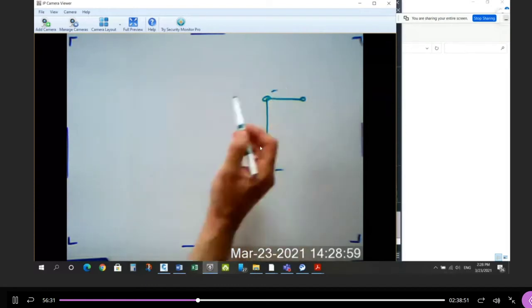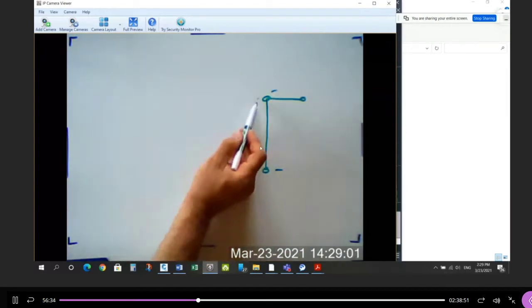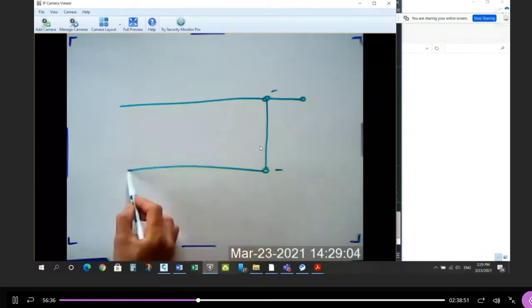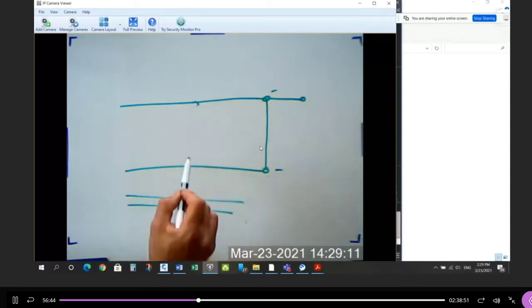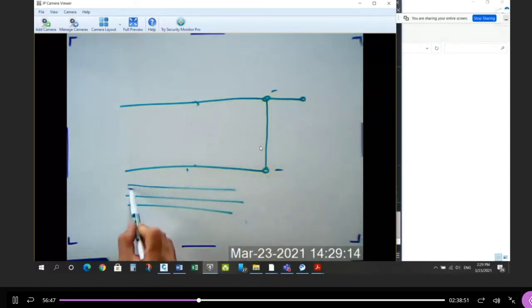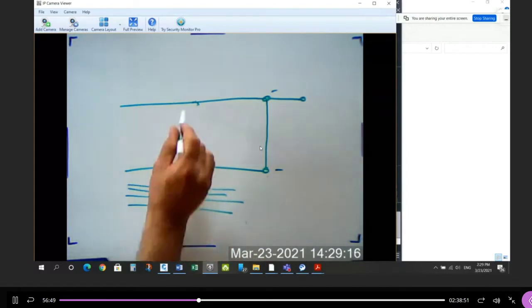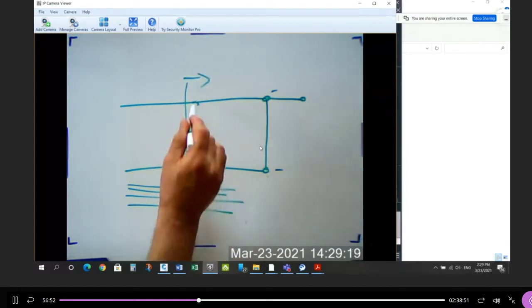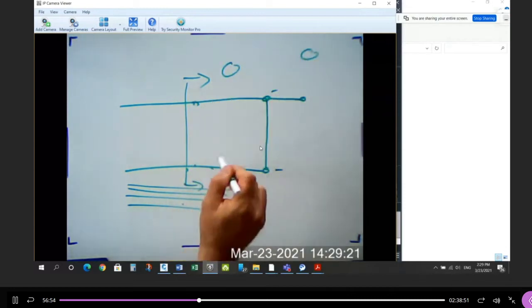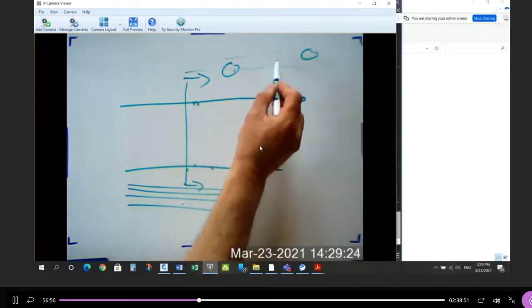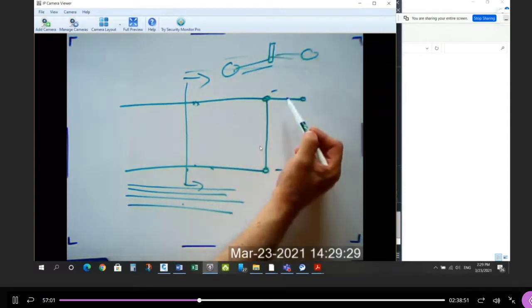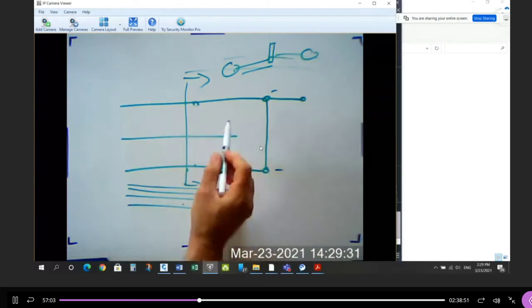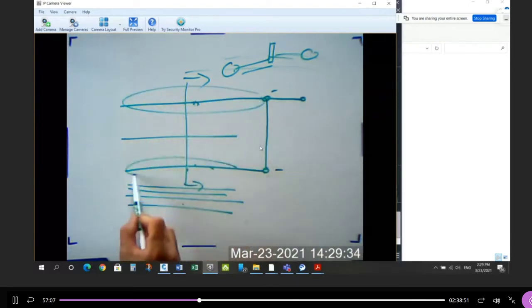Now this elevation is higher than this. This is higher than this. And now we're going to go uphill, the same slope, uphill, the same slope. This pipe is lower than this pipe. So if you look at them in profile, this pipe would be going downhill, and this pipe will be going downhill, but it would be much higher. So if you look at this cross section, this pipe would be lower than this pipe, for the same elevation. So we want to connect the catch basin in the backyard to the lower pipe, not the higher pipe. So as far as this backyard split, we want to connect to these pipes, not these pipes down here.